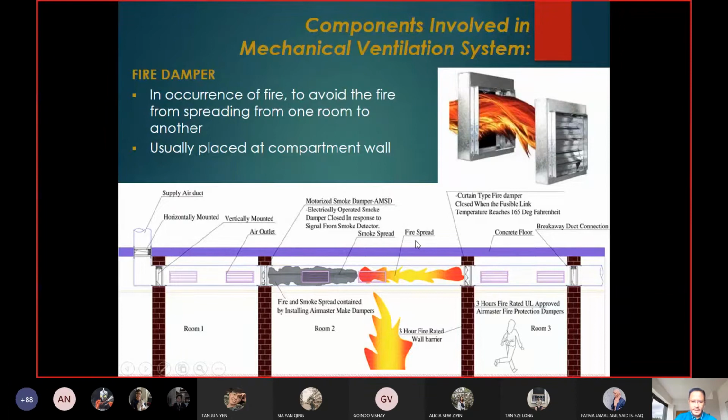So basically how the fire damper works, in normal time, this thing is folded up here, right? It's like accordion lah, if you know accordion, right? So when you compress the accordion, the blades here are folded, and everything is fixed on top of here, and then there's a sensor or a fuse link or something.